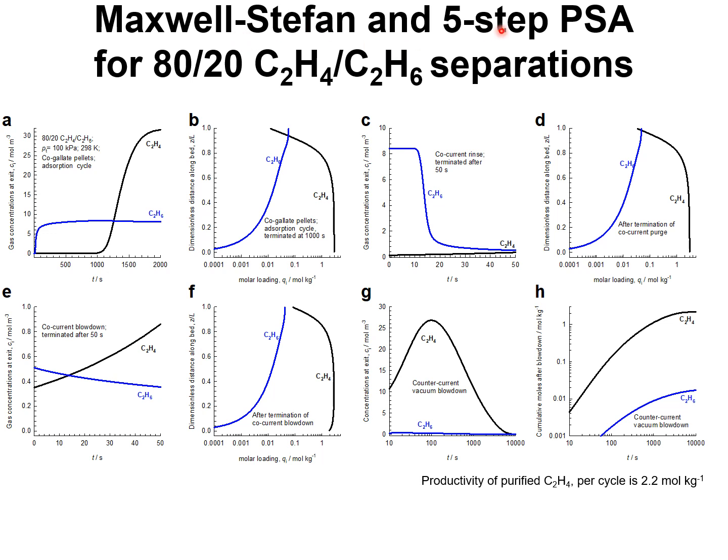And a complete 5-step PSA scheme is required for ethene-ethane separation, in which intracrystalline diffusional influences are of significant importance.